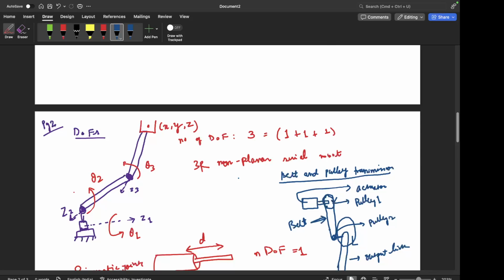Just by adding these two things, taking rigid bodies, those are the links, and attaching two links together with a joint, let's say that made our 2R manipulator, right? And I added motors on each of those joints. At this stage, I can power each of those motors independently, and I can move those two links.